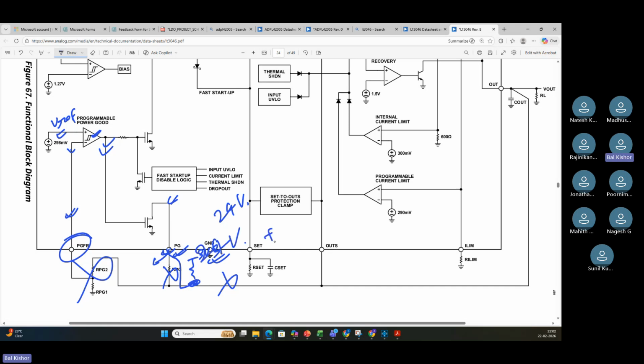Some people use plus minus 15-volt logic level, so we will use plus 15-volt also. Some people use 6-volt, some people use 5-volt. It varies, it is not common in all industries. I work in semiconductor, and there we use 24-volt. You would not have thought of a 24-volt logic level, is it? Yes, it is. Understood? So this is how it works.